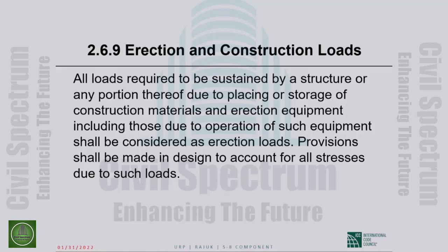It's not just that concrete building. Any building will see the highest loads it will ever see during its service life during the period of construction. That's the highest loading, because you store stuff on the floors, workers are walking around, and also the concrete is green. It hasn't quite gained the full strength that it is going to gain in time.